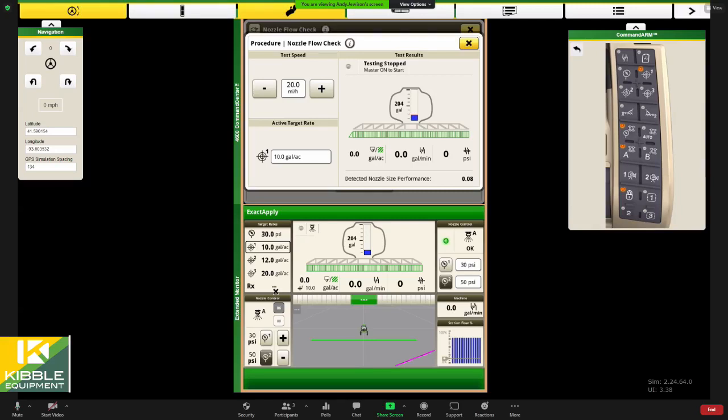But just a quick question, to clarify for everybody. That little bar graph on the bottom right-hand corner, since each nozzle body has its own pulse width modulated valve, that's the percentage of time, the duty cycle, right? Yes, the percentage of time that it's open. It's the actual duty cycle. So it's the percentage of time over a given period of time.